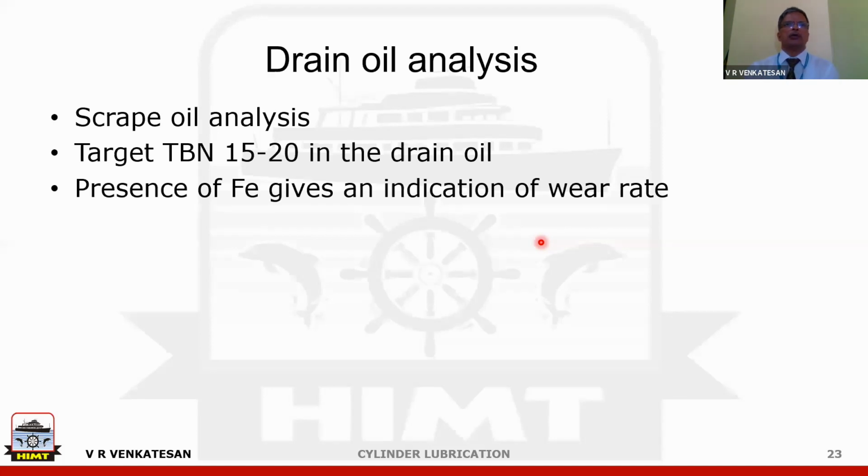the basic principle of sliding lubrication theory is there. And in all aspects, liner lubrication is difficult because it is intermittent motion and it has high load and it is also at high temperature. So it is difficult to maintain an oil film.